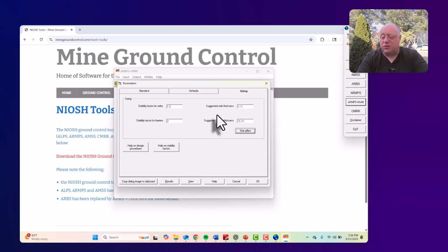But at some point, you do also want to consider that the thinner they are, the more likely you are to cross holes, in which case you would have to abandon that hole and move to the next. So keep that in mind when you're sizing these things, and that maybe you want to have a little bit wider web, a little bit narrower barrier, something like that. It just depends on how accurate the machines that you have can mine.